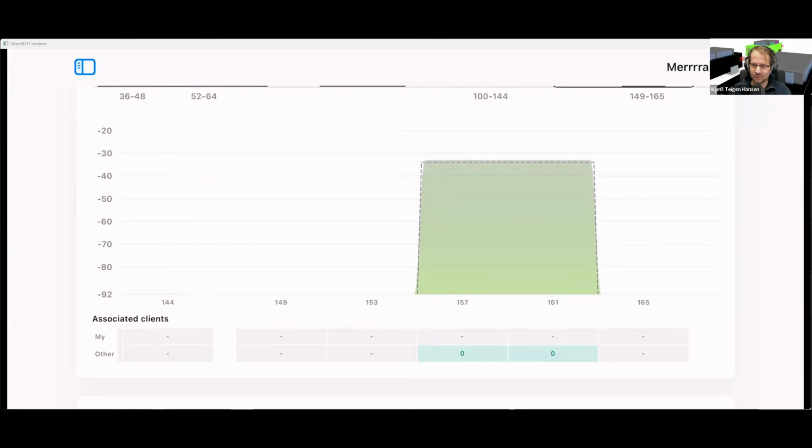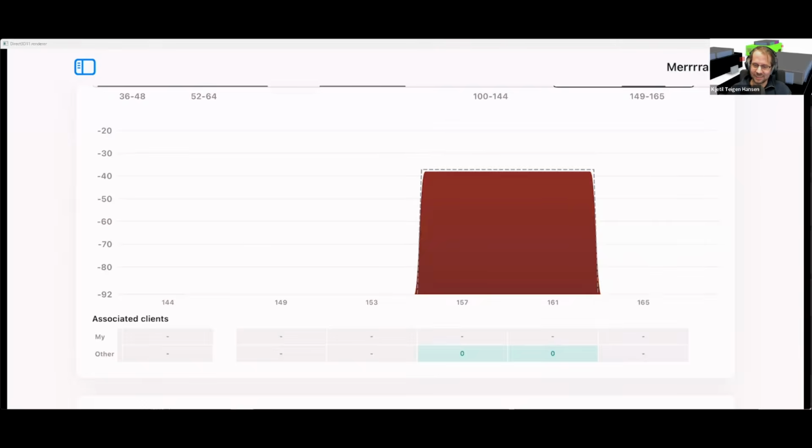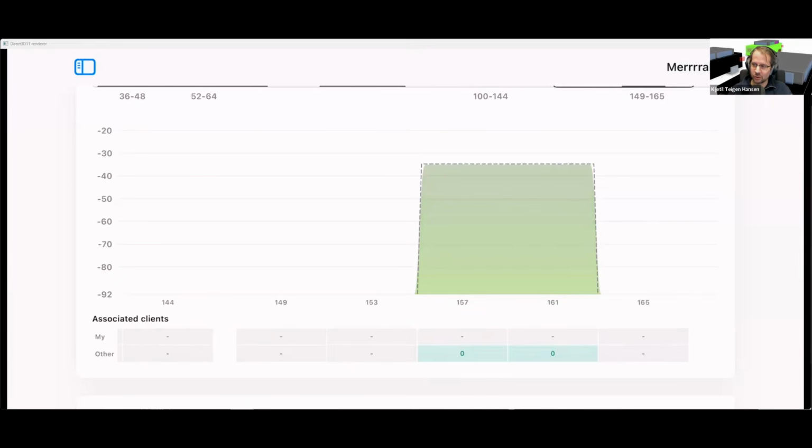And usually, when it reaches a point where you only get like one beacon every minute, because everything is broken because the signal is too strong, you see channel utilization rising. And the other interesting part is you'll see this happening before it triggers energy detect or anything else. If the application supports noise, please add it, because in Wi-Fi they look at the entire channel, they cover the thermal noise for the entire channel. So if you bring in a 1 kilohertz, a really tiny signal, it will base the new noise floor on the strength of that signal. So if it's 1 kilohertz wide, a small carrier wave, then you can see the signal.